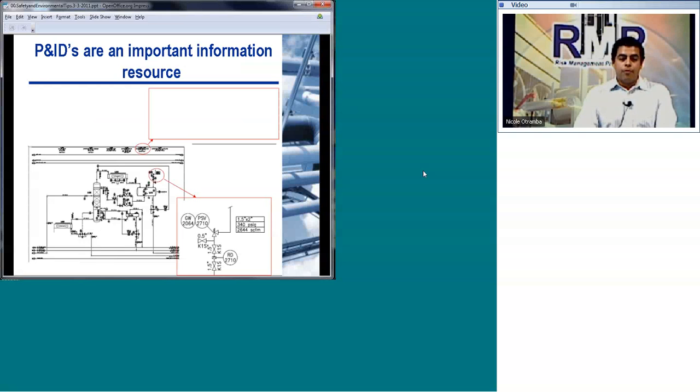This is an example of a P&ID. Basically, for the vessels, it's important, so you see the depropanizer reflux accumulator, to see the size, the material, max allowable working pressure, and that sort of information. Right on the P&ID is a really good place to have that information.